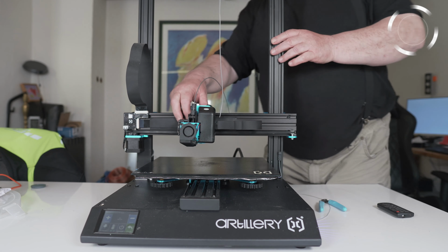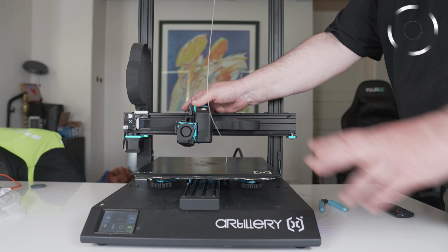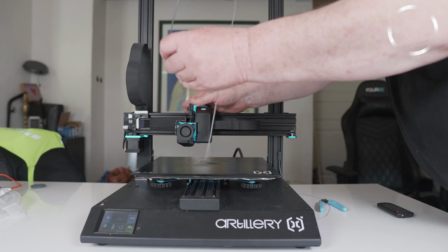I do that because we do not want too much pressure on the flexible filament, because that will cause it to buckle like that inside the extruder into the gears. So that's why I push it up quite a lot. And remember, when you load PLA or PETG or whatever, next time you need to tighten it again. Now let's see where we are, 211. The positive thing with the Artillery is it heats with 220 volts. But here we go, it's out.